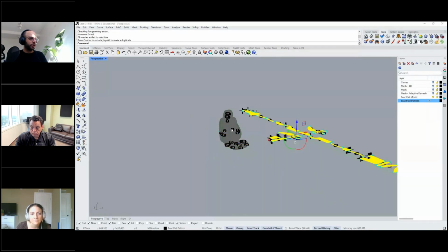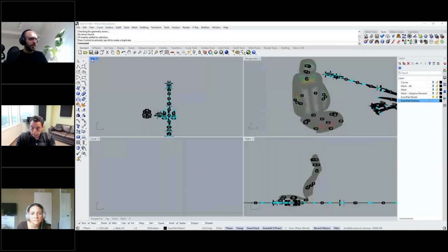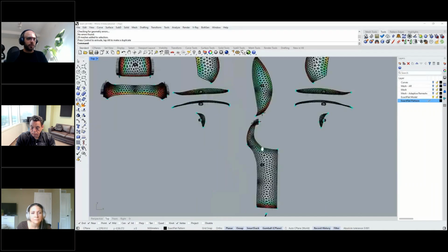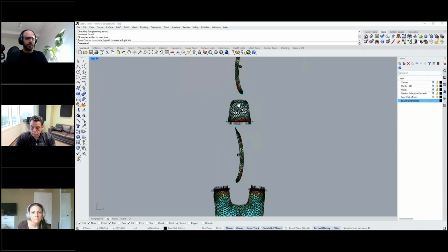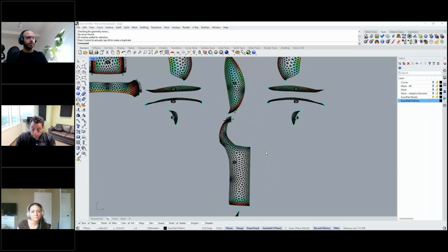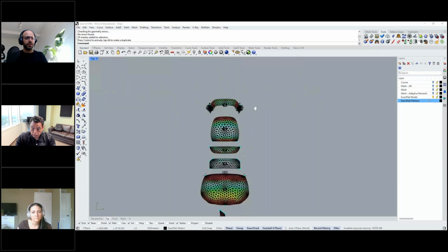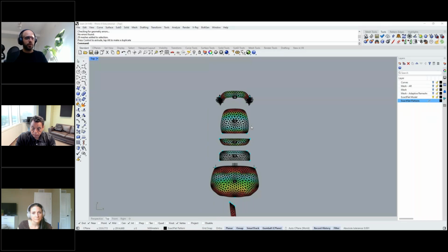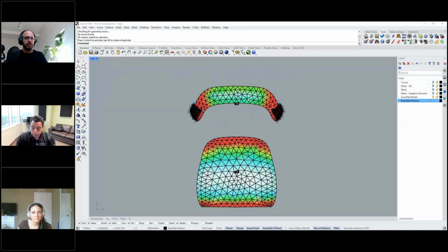And if I switch over to the top view, now we can see a preview of our flat patterns. What I mean by preview is that right now, at this very first stage of the flattening process, we are taking our pieces and dropping them on the ground or on the table. These are just very raw projections of the patterns that we want to create. So at this current stage of the process, since our patterns are being dropped on the ground or on the table, they will have folds or wrinkles, and we'll want to remove these folds or wrinkles by extending those meshes on the ground.